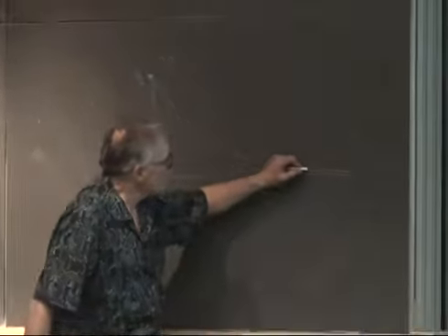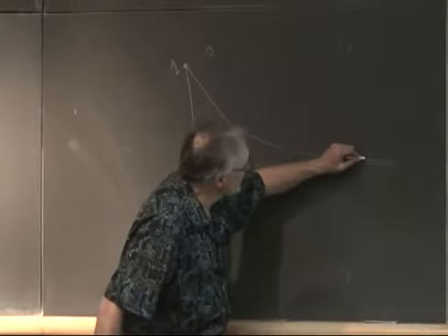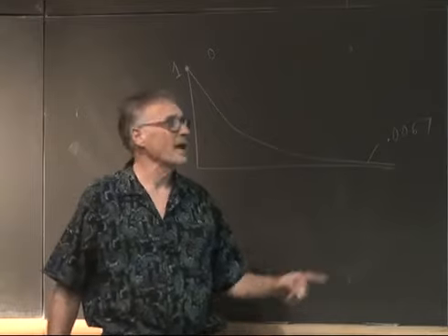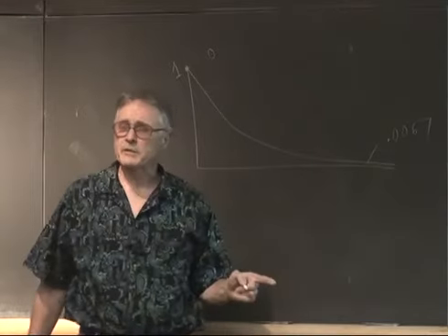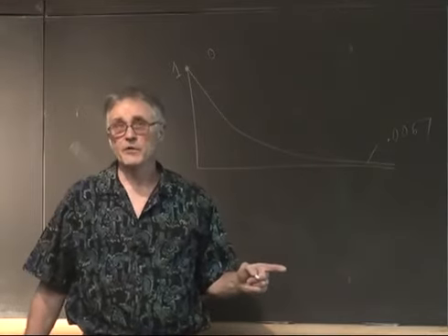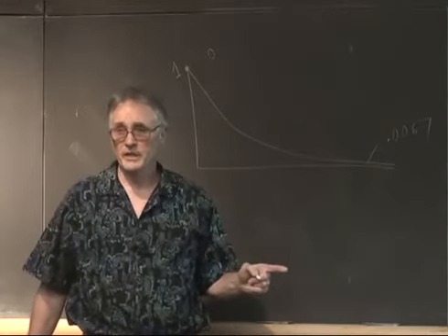And here, out of 5 time constants, we're going to have 0.0067. How many dBs down from 1 is that? That's a little over 40 dBs down. Right? It's actually almost 46 dBs down or so.